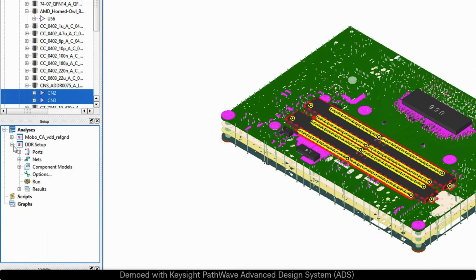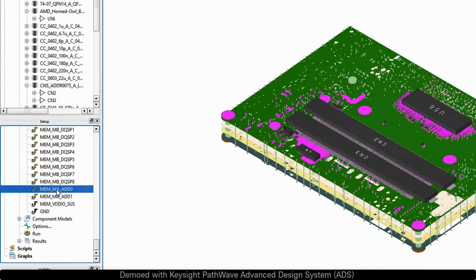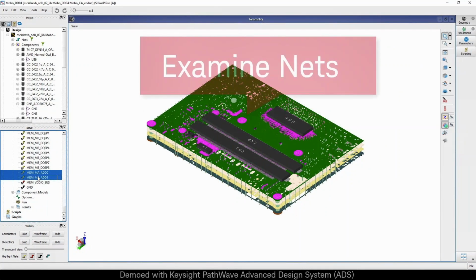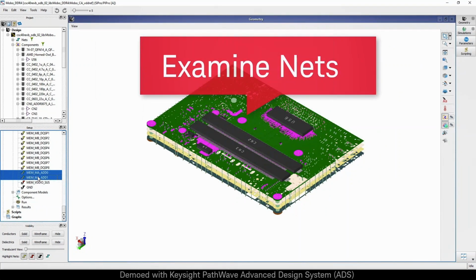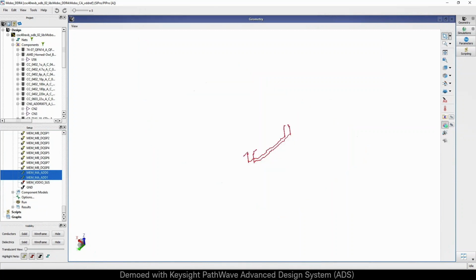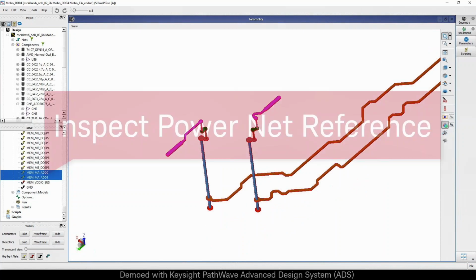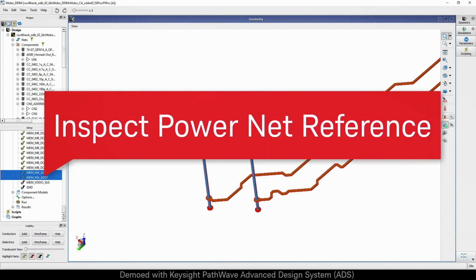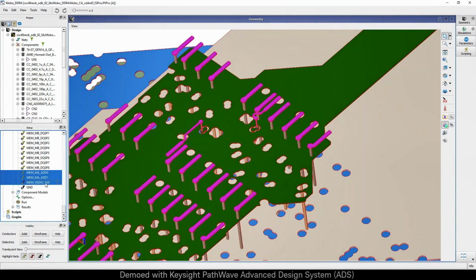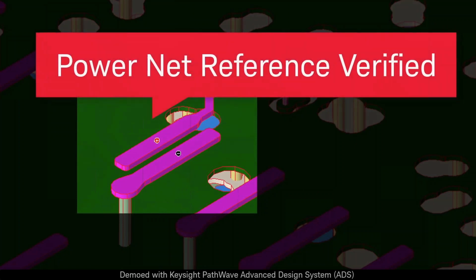So we're verifying that those additional nets were added. You see all the data nets, but we've got a couple of command address nets. Now I'm going to peel away the different layers. First we turn to a wireframe mode, turn off the connectors, then hide everything and just look at the selected nets. You can see that we've got some blind vias, but then through sequential lamination with micro vias on top, we see how it's created.